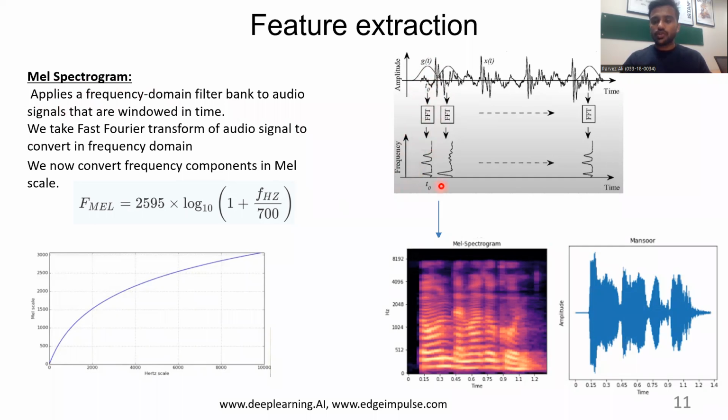When we have a frequency domain signal, it is again converted into a mel scale signal. The mel scale is better suited to human beings, as humans are good with roughly 20 Hz to 3 kHz of frequency for voice. After converting the signal into the mel scale, we get this kind of image, which is fed to a deep learning model. This picture is different for each sample, and on the basis of this picture, a speaker is recognized.